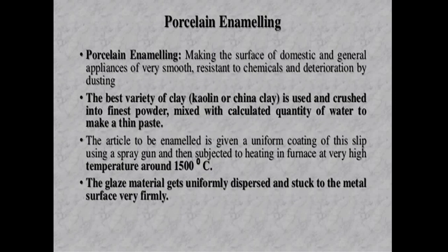Porcelain enameling is very important from your exam point of view. Making the surface of domestic and general appliances very smooth and resistant to chemical and deterioration by dusting, porcelain enameling is provided. The best variety of clay is used and crushed into finest powder and mixed with calculated quantity of water to make a thin paste.